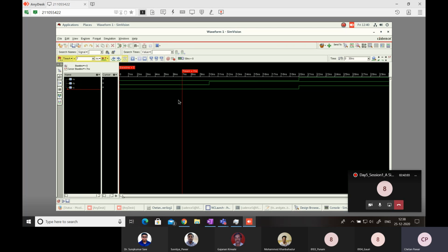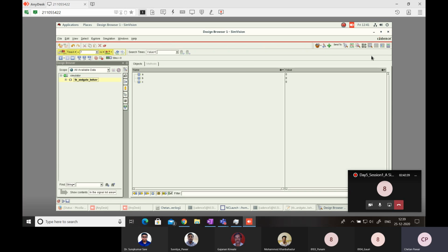So this way you can create a design and you can simulate it. So the next phase is the synthesis phase. Whatever code we have written will get mapped to the hardware. Okay, that is a very long process. So first you need to be equipped with the language very correctly, so you can write code for that particular design. Okay, so for that purpose, now you close this. You check the functionality first. Is it giving the AND gate functionality or not? Then you can close it.